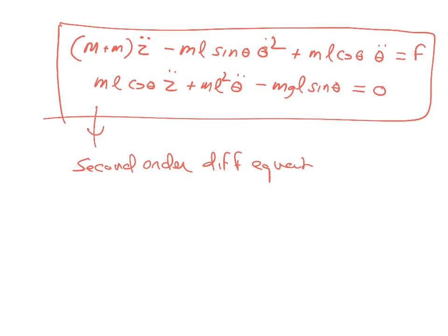What we will learn later on is to put them in a form so that we can see and tell, oh, this system is stable, or, if I do that, this is going to happen. Those will be the next steps. But this is the first type of modeling, where we get some differential equations which connect your input to the output. That's the take-home message here. Here we have second order, but this can go third order, fourth order, depending on what kind of system you have.